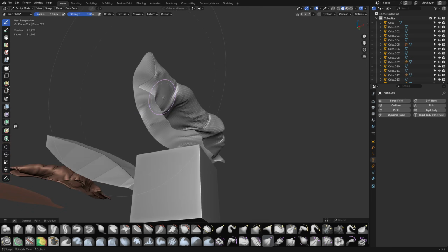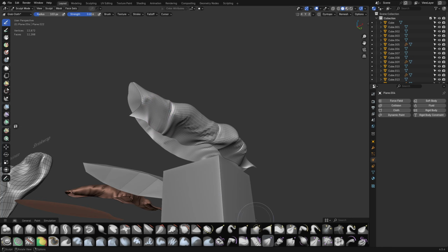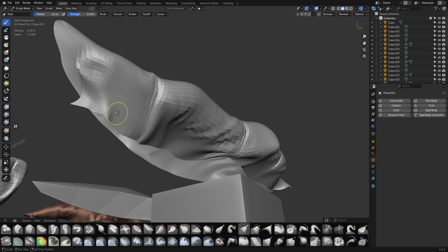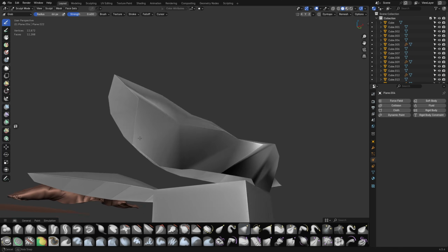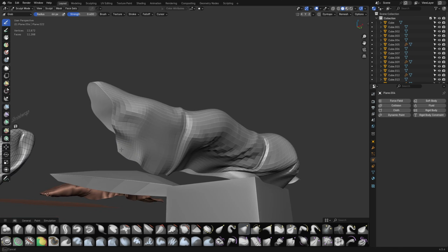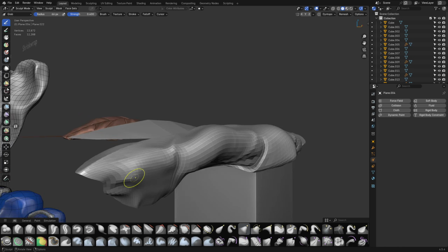It's really once you get used to modeling and you can handle doing a little bit of subdivision modeling, and you start playing around with some of the sculpt tools, you'll realize this is all way easier than you probably realize. Like this little point is driving me crazy. I'm going to sandwich it in here, try not to touch that back face over there. I'm going to try smoothing it out a little. That's a pole basically, so we just got to get rid of it.